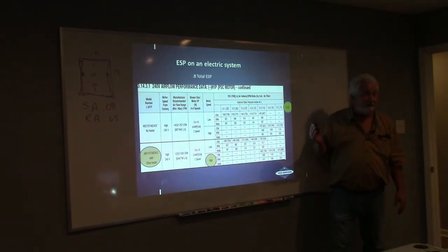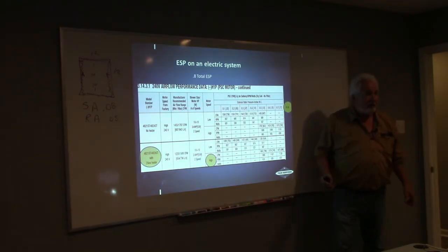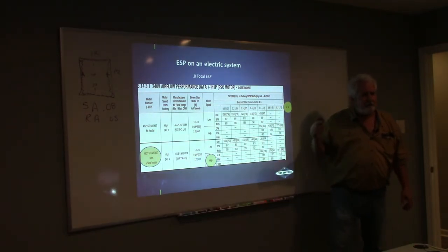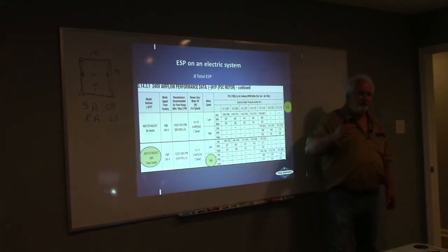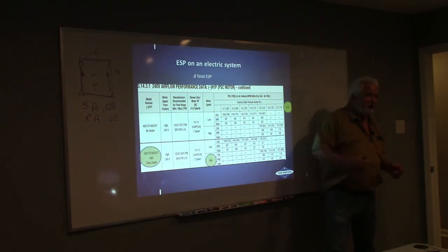What's still running? Compressor. Okay, the compressor's running outside, blower's not running inside. Nobody knows any different because the homeowner doesn't have a clue, right? So this is not running, that's running. All of a sudden, we're pumping all this liquid up into the evaporator coil. And what's supposed to evaporate that back into a vapor? Air. Oh, the heat from the house. And if I don't have a blower moving that across, that liquid refrigerant goes all the way up. How much superheat do I have? None, because it doesn't superheat at all. I'm dumping that liquid right down that suction line, right back onto that scroll, and the compressor goes out.